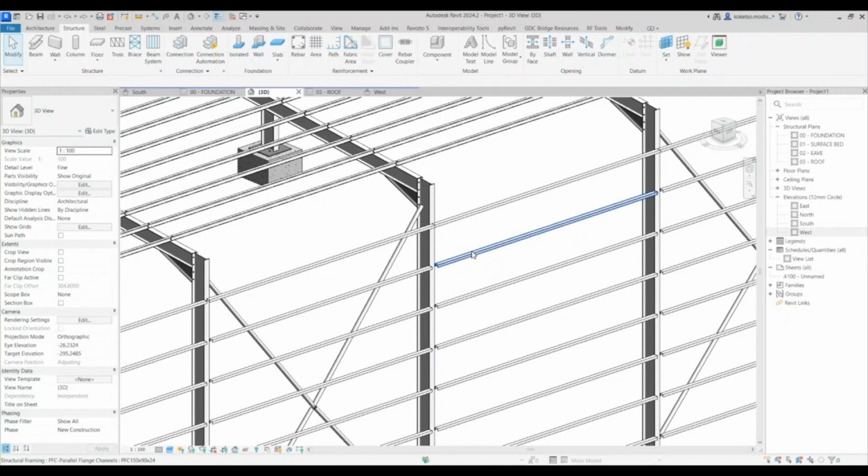So it finished generating those connections for the purlins. Now the next thing is we're going to apply connections towards our bracings. But before we do that, we have to connect also our purlins right at the end. So I'm going to select connections and then this rafter, and then I'm going to type in single tertiary angle and press enter. And this is what we have. So I'm going to right click and say propagate connection, and then it's going to propagate connections towards the other ones.